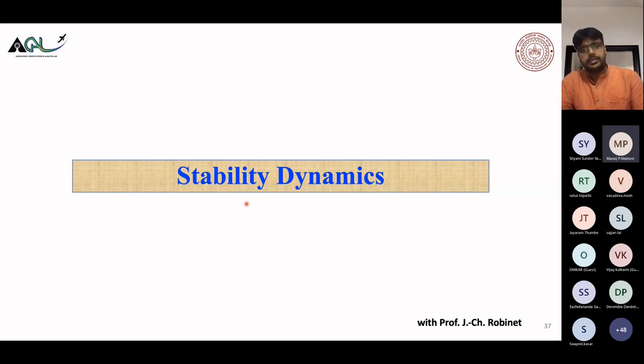The linear stability tool was used to understand if there is any mode present in the flow which can make the flow unstable and hence transitional. You would often hear the term critical Reynolds number. The flow below the critical Reynolds number is stable, and above the critical Reynolds number is unstable. We'll be using the same concept here, but here the flow is no longer laminar. Here the flow is a mean turbulent flow.